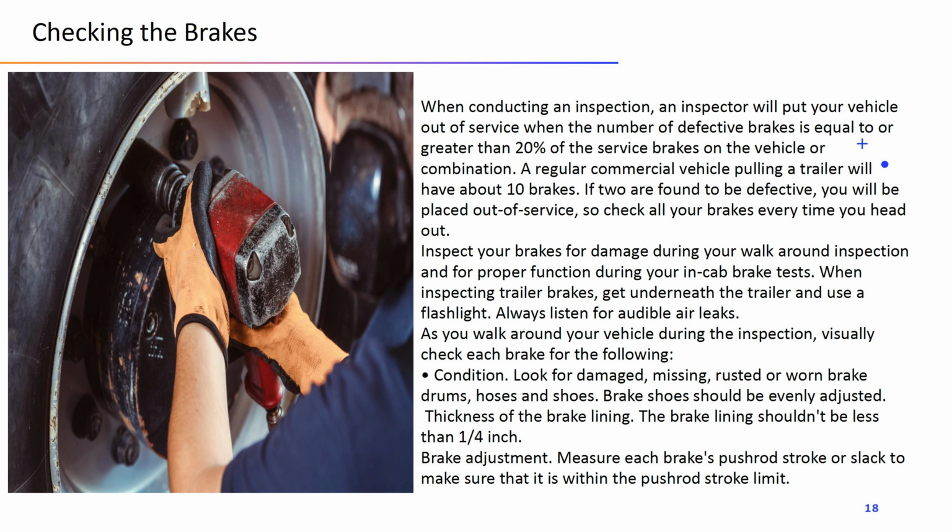Checking the brakes. When conducting an inspection, an inspector will put your vehicle out of service when the number of defective brakes is equal to or greater than 20% of the service brakes on the vehicle or combination. A regular commercial vehicle pulling a trailer will have about 10 brakes. If 2 are found to be defective, you will be placed out of service, so check all your brakes every time you head out.